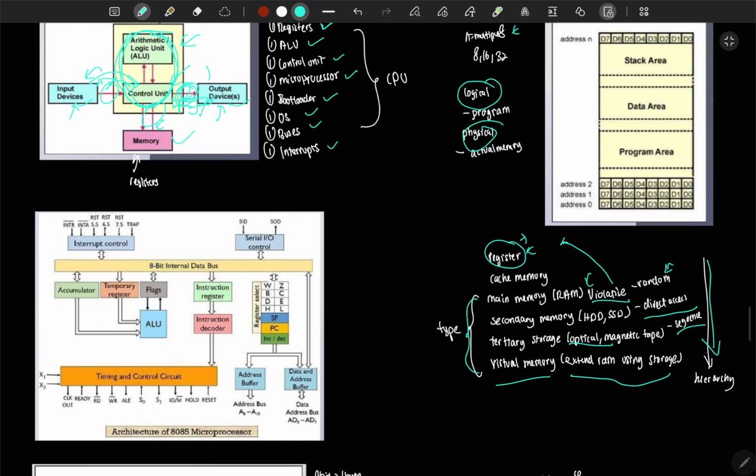As I said, this is the architecture of the 8085 without WZ. We have register pairs B, C, D, E, H, L, and these can be paired. We only pair B-C, D-E, H-L. We just take the one that's beside them. And this H-L, sometimes we call it memory. So H-L is specifically used for memory.